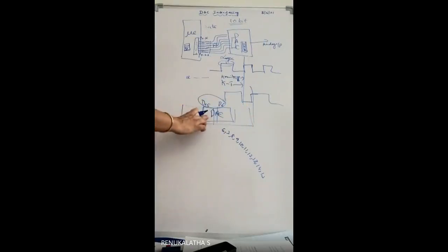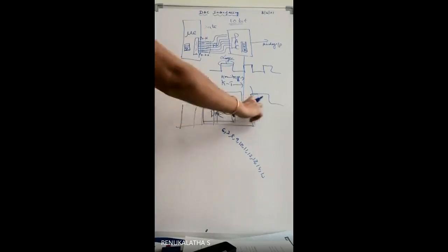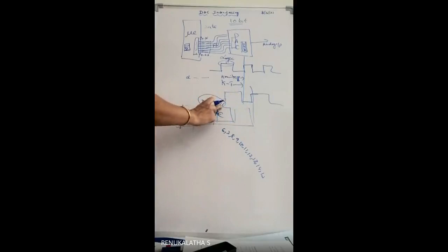What is the DAC register? The DAC register is a 32-bit register. Among all the 32 bits, only the bits from D6 to D15 are meant for receiving the data from the microcontroller, so totally 10 bits. Even if you send only 8 bits, the upper 2 bits will be added, and even if you add the upper 2 bits, it doesn't change the magnitude.